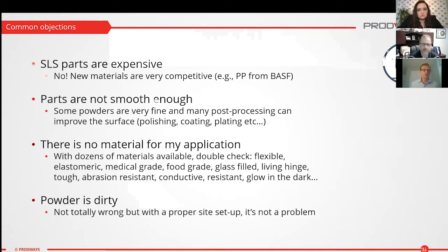Finally, powder is dirty. That's something we hear a lot. And well, it's not totally wrong. You know, managing powder is more complex than managing FDM, where you just have a roll of filament. But with the proper setup, if you organize yourself around the powder management, that's fairly under control. And yes, it's an industrial product, but it's something you can totally put under control. You just need to plan ahead and be able to address the powder in your system.